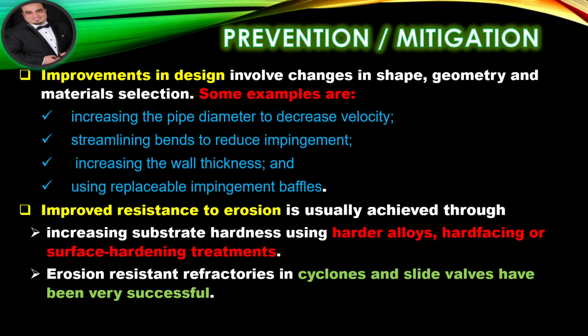Improved resistance to erosion is usually achieved through increasing substrate hardness using harder alloys, hard facing or surface hardening treatments. Erosion-resistant refractories in cyclones and slide valves have been very successful.